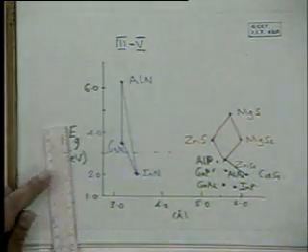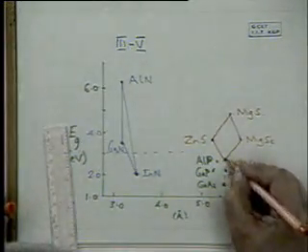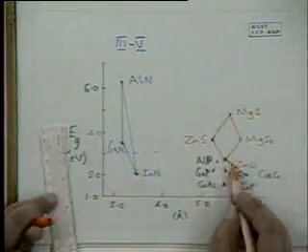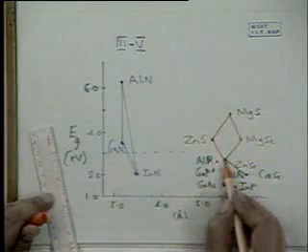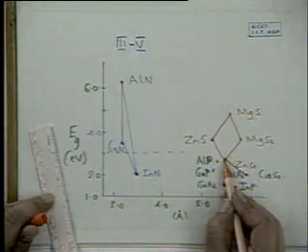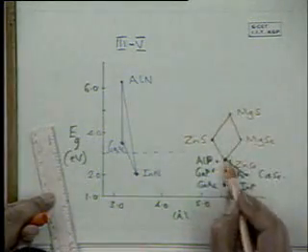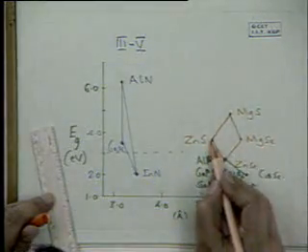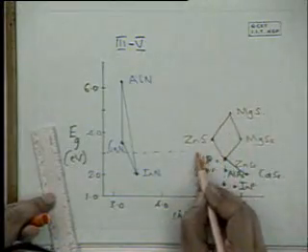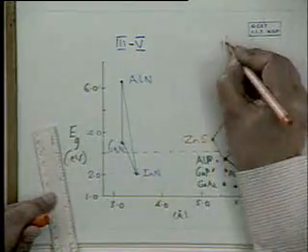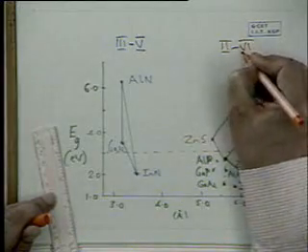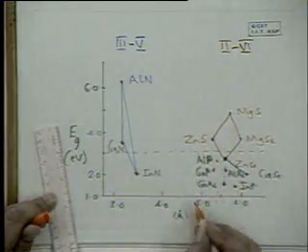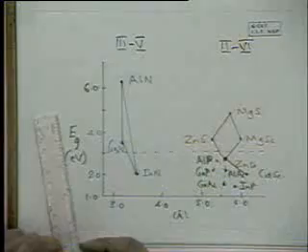So one can grow, because of this lattice match, zinc selenide on gallium arsenide. This is almost vertical. And if you're going towards zinc selenide, the band gap is just less than 3 eV. So in order to get into the blue region, you have to alloy zinc selenide with either magnesium selenide or zinc sulfide, etc. So these are the 2-6s, which are very useful for both LEDs and lasers in the shorter wavelength region.